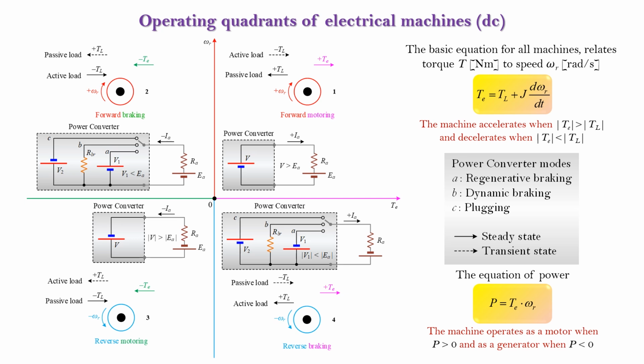Note that the torque on the passive loads is opposite to the direction of rotation. The active loads, on the other hand, are the ones that cause the machine to rotate. Furthermore, the load torques denoted by a continuous line cause the machine to run in a steady state. In contrast, the machine only operates for a transient period with the load torques denoted by a dashed line.